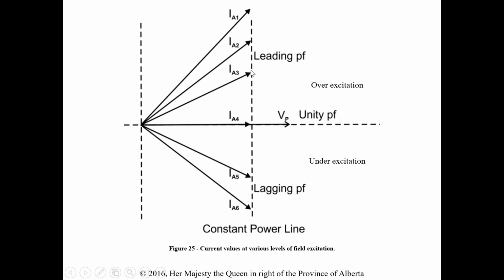power that we need to drive that mechanical load, but we potentially will have to increase the current to provide for magnetic fields, whether we're leading or lagging with our VARs. Okay, so there is that constant power there still, but we do have to change our current to maintain that if we get away from our unity. Okay, again, over excitation, we're going to get into a lead. Under excitation, we're going to get into a lag. But again, we would not want to operate in this area.